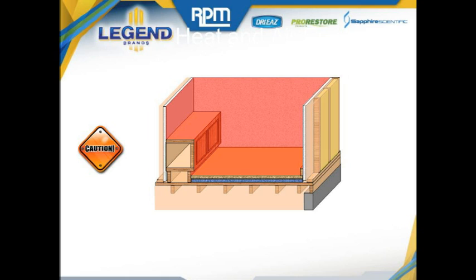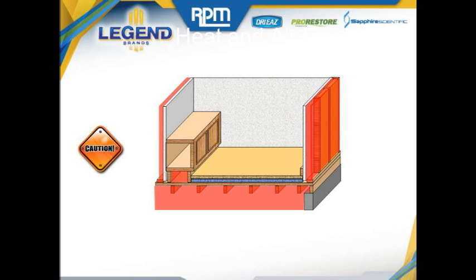As the air moves into these spaces that are cooler, the humidity relatively will increase, and condensation and secondary damage become an exceptional possibility. The primary concern with these areas now highlighted in red is that they were not affected initially, and because they were not affected, they are not being monitored by the restoration technician. Moisture driven to these spaces by the high temperature and vapor pressure are now going to allow water vapor to condense and absorb into these unaffected materials. They'll go unchecked and undiscovered and cause secondary damage that will be discovered in the future.